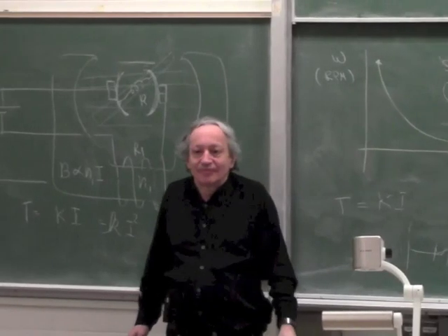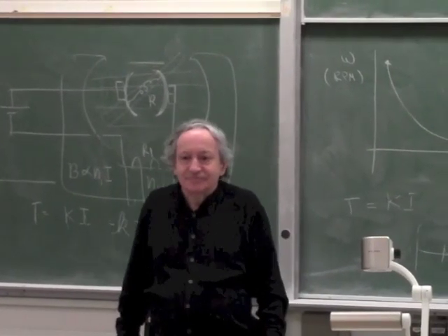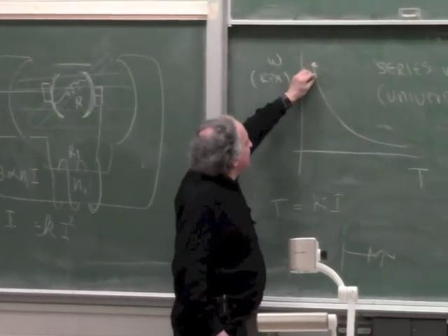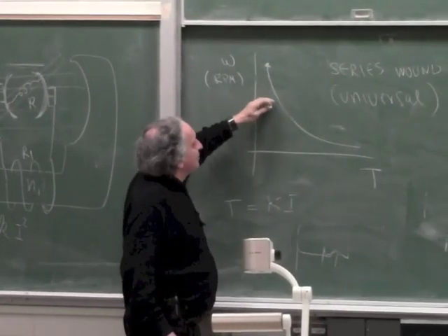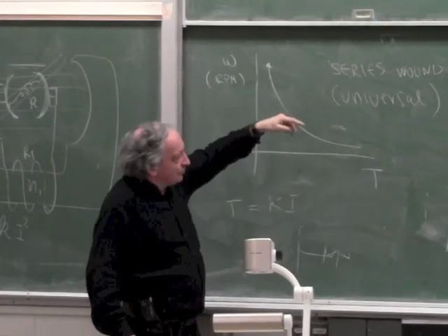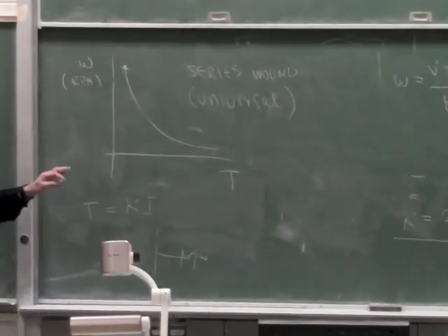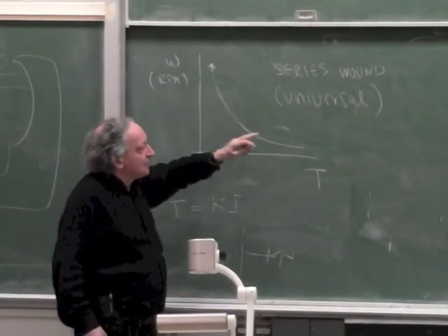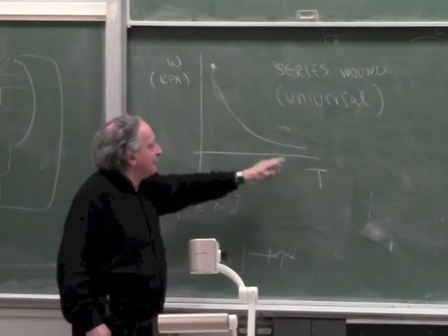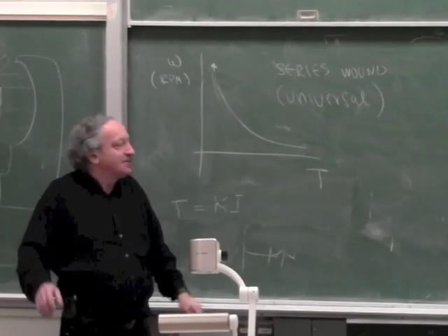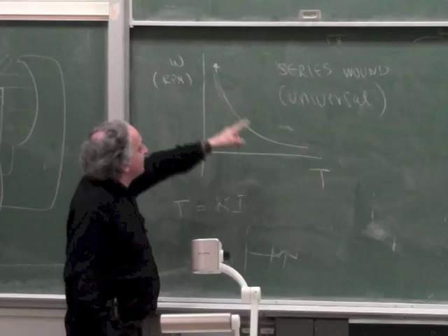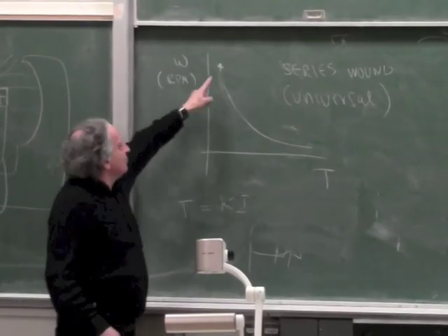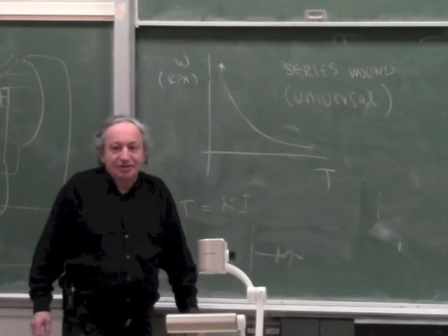Yes? Is there some danger at that moment when you put in the load, like in the transient? No, because it's a continuous curve. The moment there's a bit of load, immediately the speed will go down. But if you do the full math, which I'm not going to do right now, you find out that if there was no resistance, it was exactly a curve of constant power. If there was no resistance, this curve would be exactly omega times T equals constant. Okay? So nothing happens. It just moves up and down on this curve as the load changes.